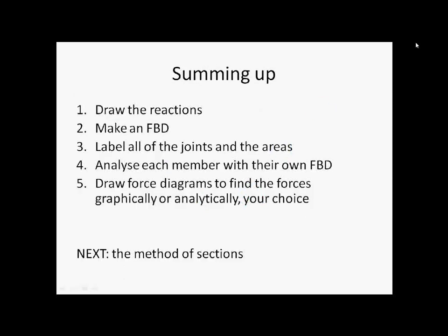Summing up, first you draw the reactions, then make a free body diagram, then label all the joints and the areas, then you have to analyze each member with their own free body diagram, and draw force diagrams when you need to find the forces graphically or analytically. It's your choice. Coming up next, we'll look at the method of sections. Good luck with your studies.